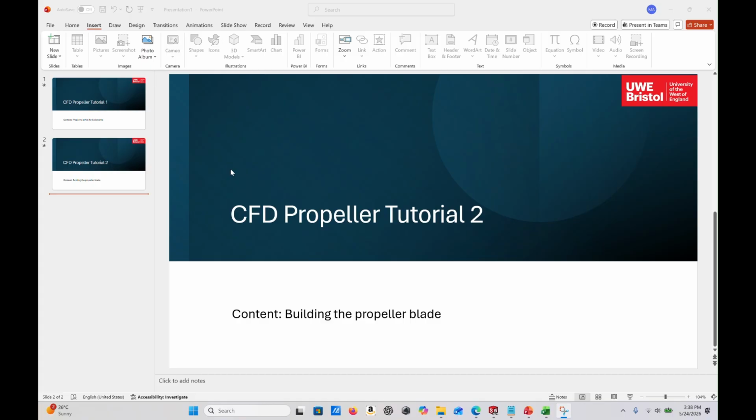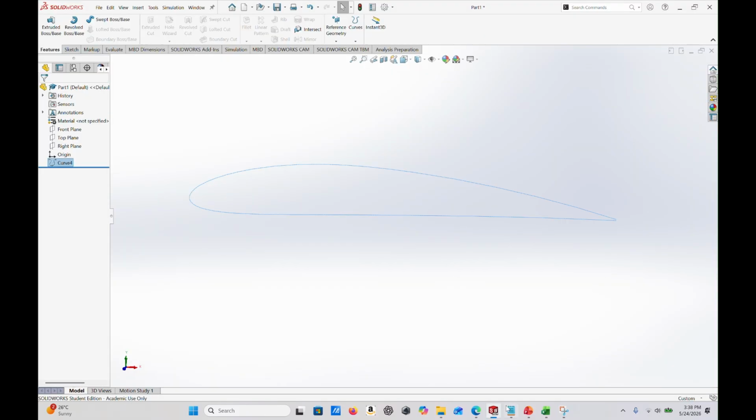We are now gonna start building the propeller after what we left off from beforehand, which was making the curve using airfoil tools. Now we're gonna start by first going to SolidWorks, and as you can see, if we go onto the trailing edge, there is a bit of a gap, and we need to fill this gap as well, because of course we need a solid surface, a closed surface, so we can at least extrude to 3D.